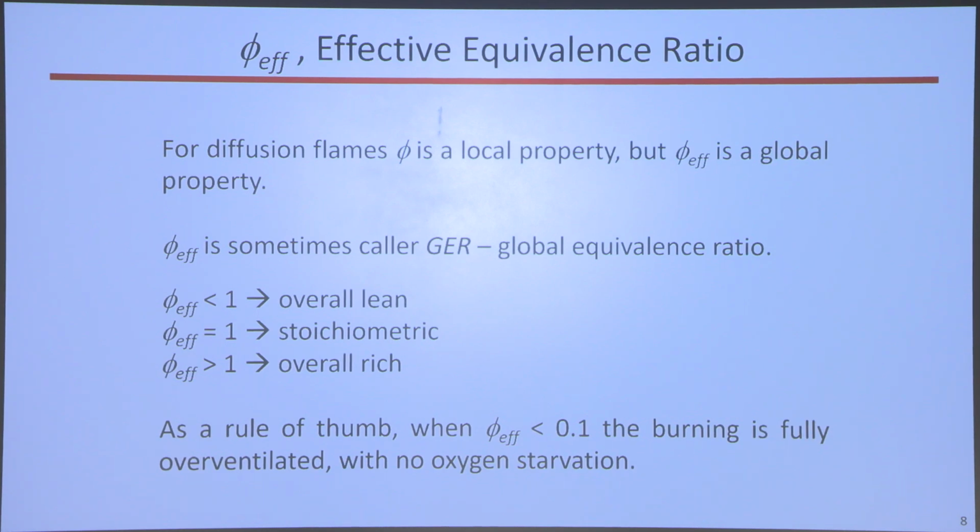A good rule of thumb we use for fires is that flames like to have about 10 times the stoichiometric air. If you burn a fire in a chimney in your house and you do the measurement, you'll find that the amount of air that gets pulled into that chimney is about 10 times stoichiometric. So that means, when you have a fire, you're usually pulling a lot of cold air from elsewhere in the house. You may be actually cooling down your house and forcing your heating system to work harder. But it's the same for this burner.